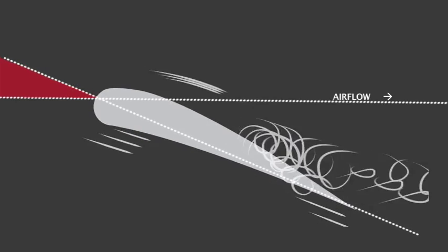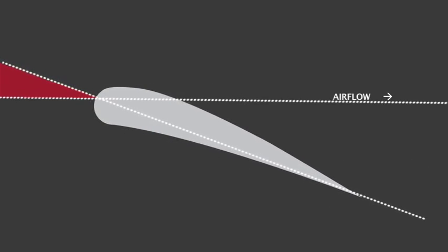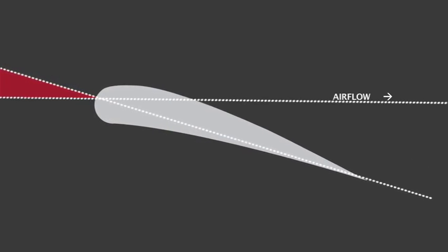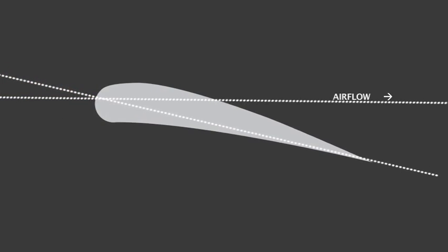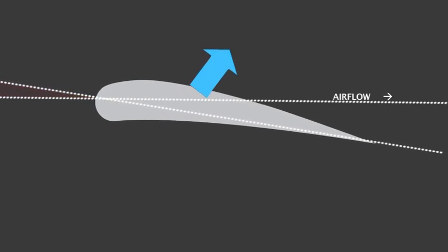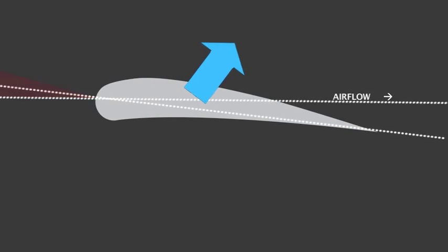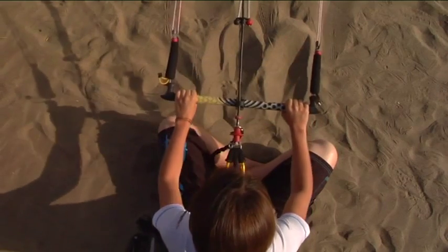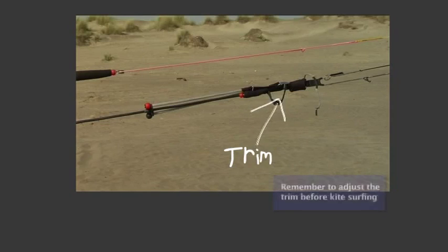At a certain limit, the power of the kite will be reduced enough to prevent flight. You must remember to push your bar to return to an acceptable angle of attack and to remain in flight. You will lose flight capacity if you pull too hard on your bar. Thus, it is important to adjust the trim according to the wind speed so that you are not suddenly overcome.